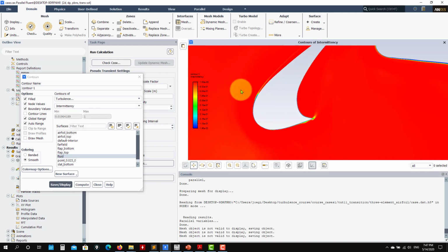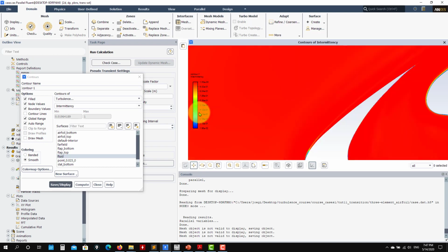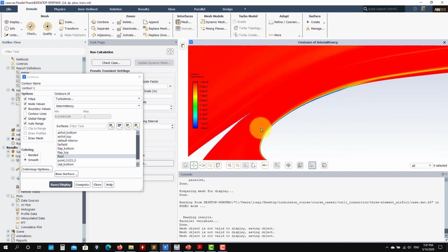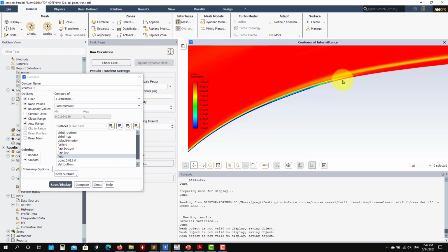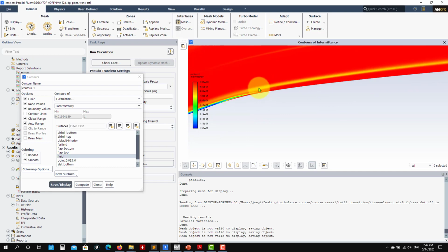When you plot the friction coefficient, for instance, you are going to see that here it is probably laminar, smaller, and then it becomes larger here. So if we move here, see again, here it is better to appreciate this transition model working: laminar, then you have the onset, and then it becomes fully turbulent, okay?